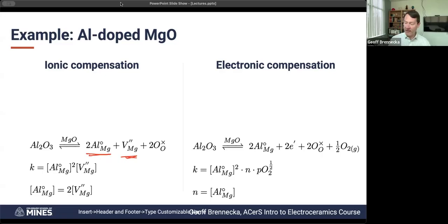And so if we have that same magnesium oxygen lattice, and then we yank out two of those magnesiums and put in two aluminums, now we're actually taking out a third magnesium, and this becomes a vacancy. That one becomes aluminum, that becomes aluminum, but we brought three oxygens along with that aluminum, so all of the sites are still filled.